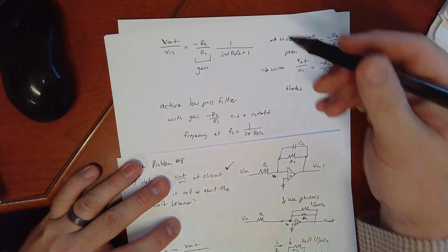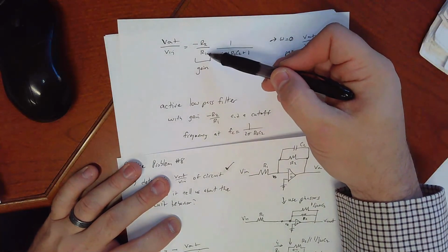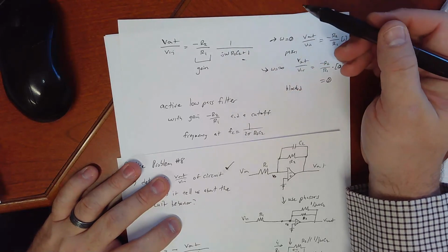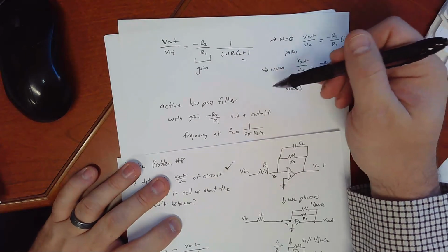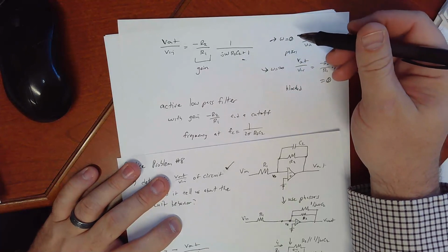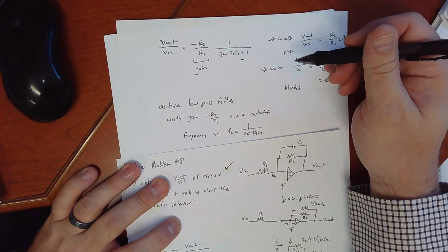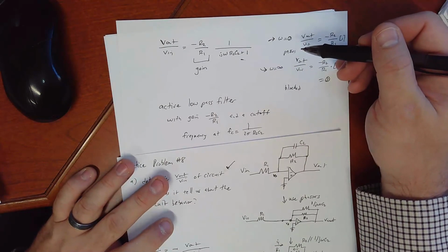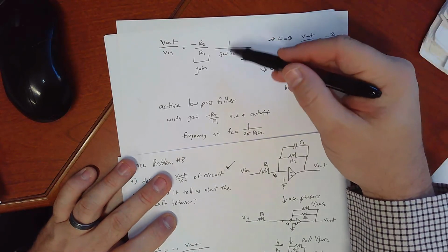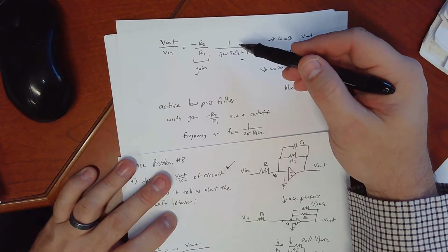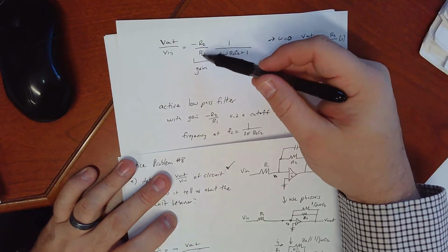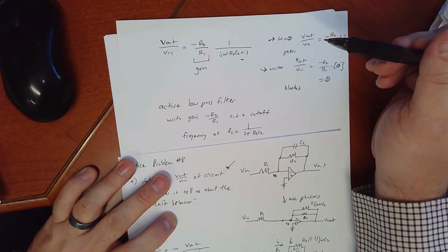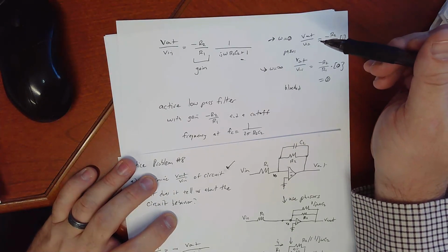Now that's interesting. See, so the combination of resistors sets our gain, but then the capacitor and only R2 set our frequency. So we can independently tailor our gain and our frequency. So that's what's really happening here. And all we did was substitute a capacitor. So not only do we get the same low-pass filter behavior we saw in a previous practice problem, we also get the gain behavior of the op-amp. So we get the best of both worlds. That's pretty interesting. Pretty cool, right?